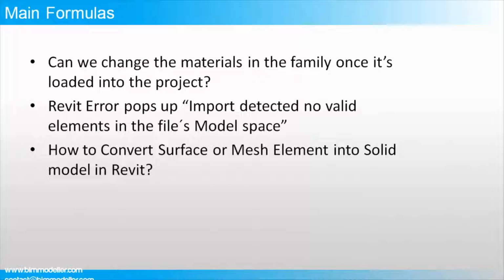Another is the Revit error pop-up: the import detected no valid elements in the file model space. This comes up mostly with 2D files, so make sure that you have the proper DWG file, with proper 3D elements available in the model, while checking the DWG file.